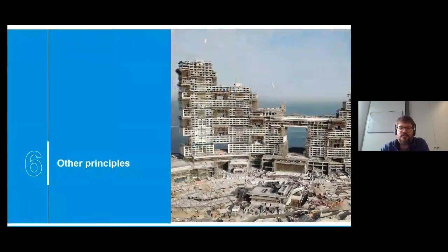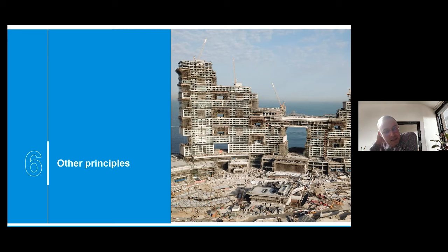Any other question? If I may ask a question, you've been mainly focusing on durability, but in high-rise buildings, I think you can also have problems with long-term deformations. Yes. Because you have so much concrete stacked on top of each other. So if it starts creeping and you're not entirely certain what the value of the creep deformation will be, you could also get some problems, I think. Is this something you also take into account with the mix design?